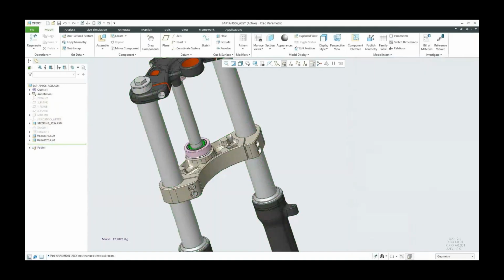But that's an interchange assembly. If you've got light components, obviously for 3 or 4, you could probably get away with just swapping those out manually. It doesn't take too much. But if you've got 100 different models that you're always swapping in and out, you get some real time savings when you're working with these interchange assemblies.